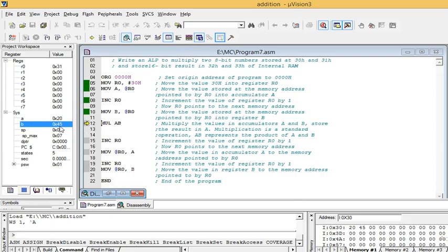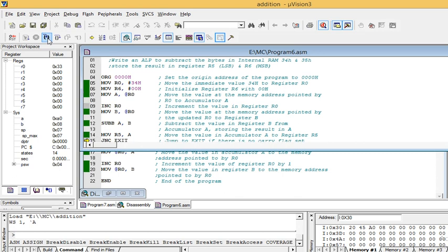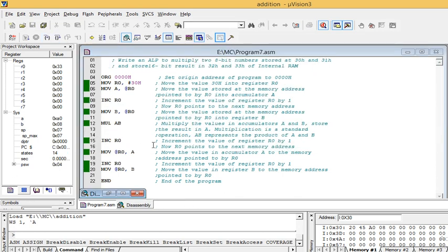Now we need to multiply A and B. The data will be stored across A and B by default. As I told, in the calculator, if you multiply the two hexadecimal values, we are going to get 08 and A0. Now getting that, we are going to move the same value. And this is the end of the program. Thank you.